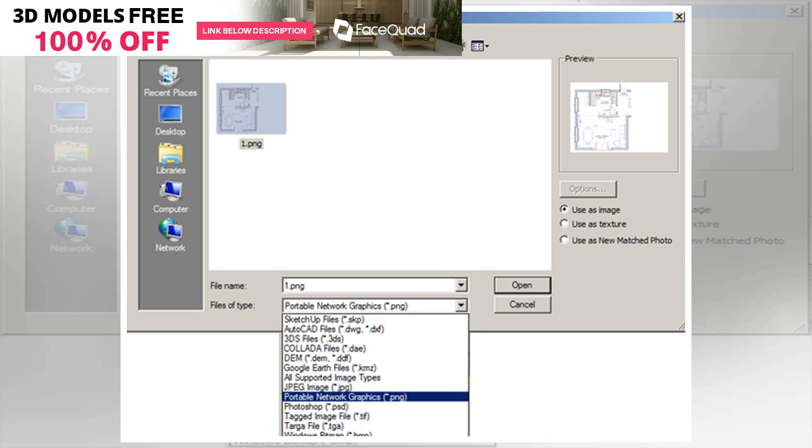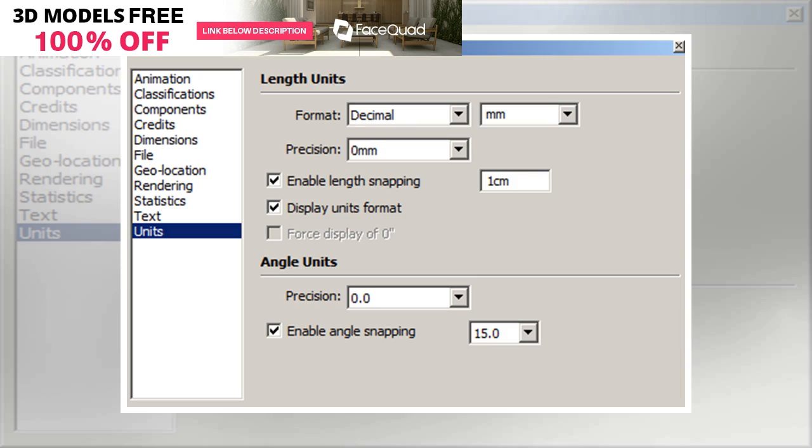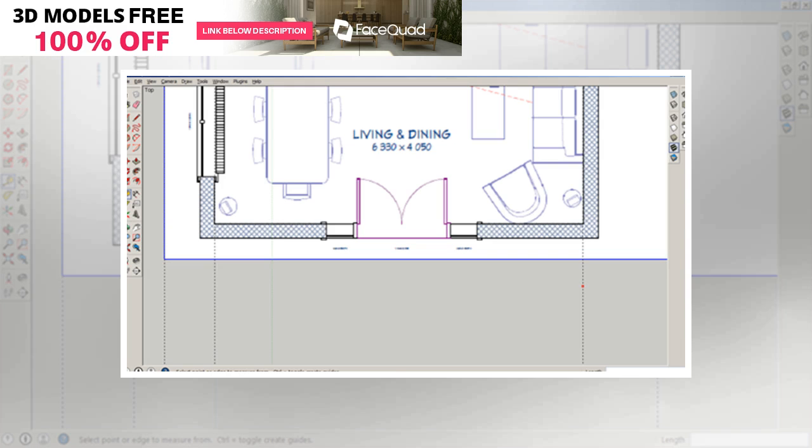Using shortcuts will significantly boost your performance. But it's up to you whether to memorize them. Instead, you can reach tools via Toolbox. Go to Menu Window / Preferences / Shortcuts if you need to manage shortcuts. Now, let's get to modeling.